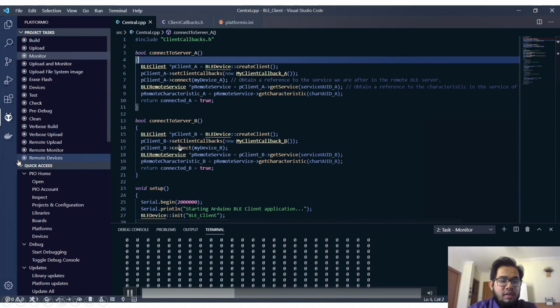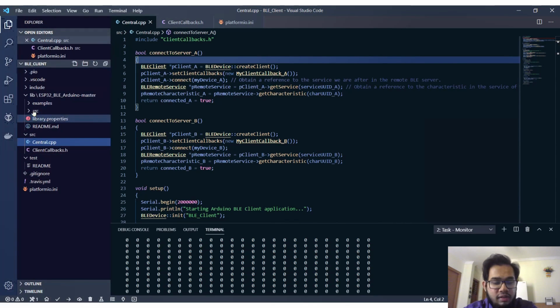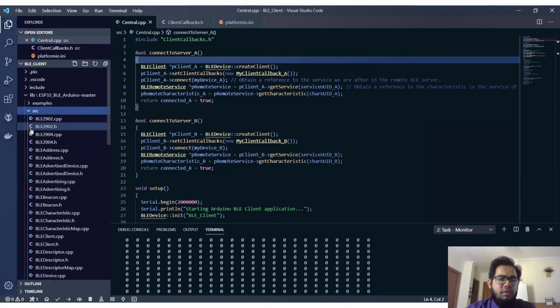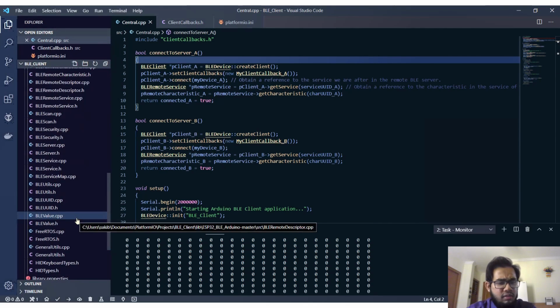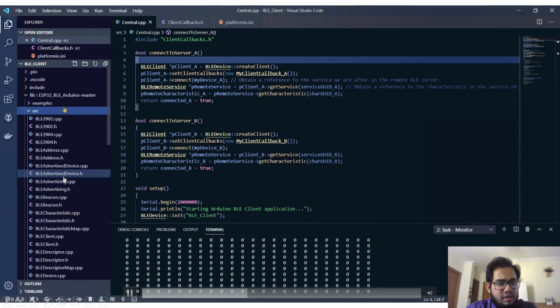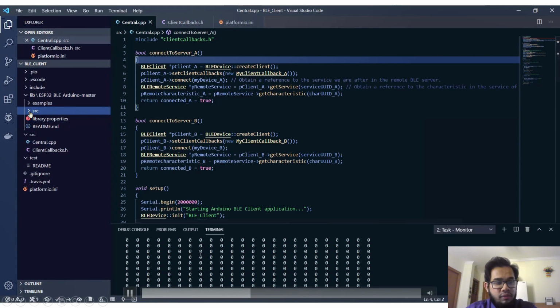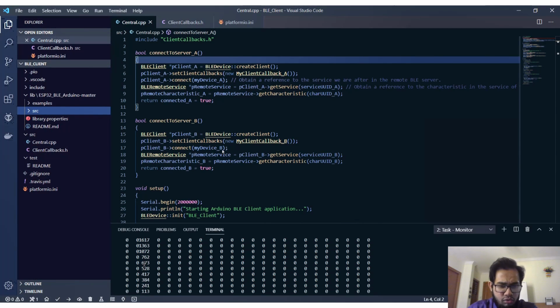In this setup, I am just sending data from one FSR which is connected to the third pin of the multiplexer. So all the list of libraries is also included in the project. When I press the FSR, you can see the values are changing. It should go to a maximum of 4095, which is the 12-bit ADC of the ESP32.